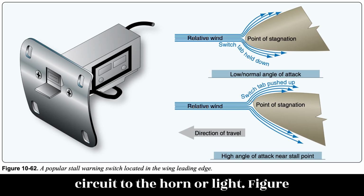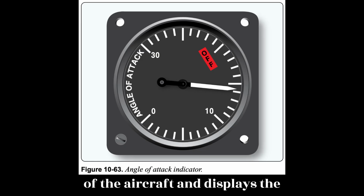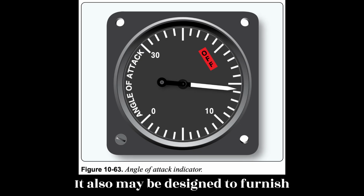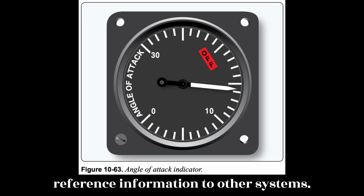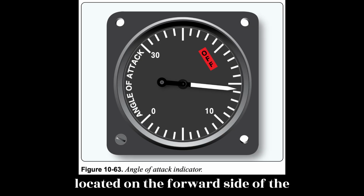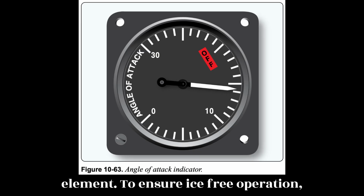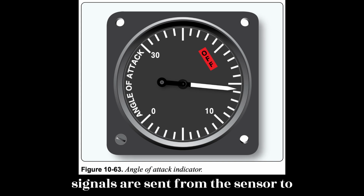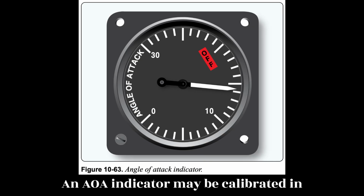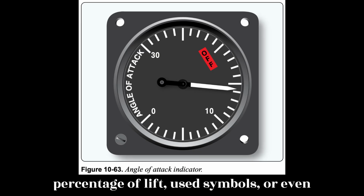Figure 10.62. A true AOA indicating system detects the local AOA of the aircraft and displays the information on a flight deck indicator. It also may be designed to furnish reference information to other systems on high-performance aircraft. The sensing mechanism and transmitter are usually located on the forward side of the fuselage. It typically contains a heating element to ensure ice-free operation. Signals are sent from the sensor to the flight deck or computers as required. An AOA indicator may be calibrated in actual angle degrees, arbitrary units, percentage of lift used, symbols, or even fast/slow.